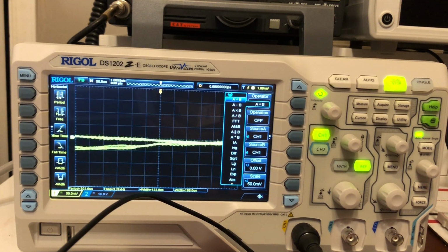FFT. So fast Fourier transform is used to transform time domain signals to frequency domain components, or frequency spectrum. This oscilloscope provides the FFT operation function, which enables users to observe the time domain waveform and spectrum of the signal at the same time. FFT operation can facilitate the following work. You can measure harmonic components and distortion in the system, you can display the characteristics of the noise in DC power, and you can analyze vibration.